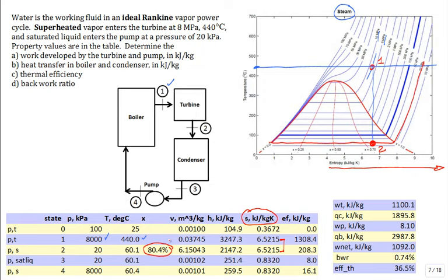You could superheat it a little more. Superheat it out to, I don't know, 500, 540, 600, and see, as it nudges out, maybe it gets up to 85, 90, 95%. But don't superheat it so much that it comes way out here. That's not good for performance. Okay, that's state 2. Where is state 3 on this diagram?